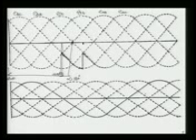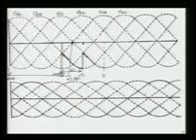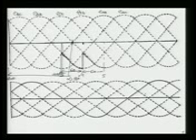Again 60 degree here, where your valve 5 is fired, here valve 4 is fired. We are writing the valves where it is giving the gate pulses, because you can see the difference between here and here, it is 60 degree. So next 60 degree here, and it is a sequential firing, means 3, 4, 5, 6, 1, again it is a cyclic one. So it was here, it was coming here, then it was coming here, and now we have reached here. Now your valve 5 is getting pulse.